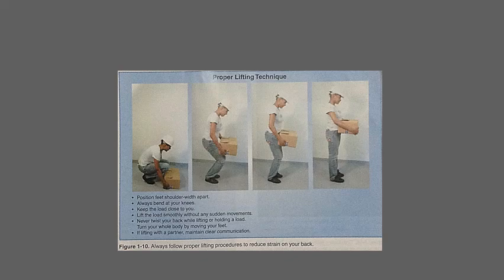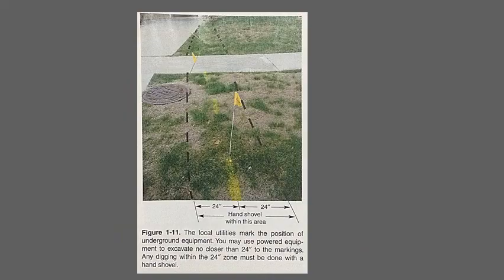Always notify the local utility before digging. They will mark the ground where any electric cable lines, gas lines, water pipe, or television cable lines are buried. Do not use any powered excavating equipment within 24 inches of the utility markings, such as in Figure 1-11.